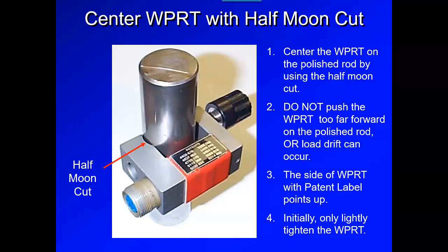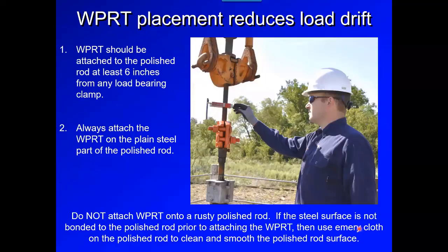Okay. Now, step 4 is only lightly tighten the polish rod transducer. So get it up there, adjust it just a little bit, because we will do a little bit more finite tightening in just momentarily.